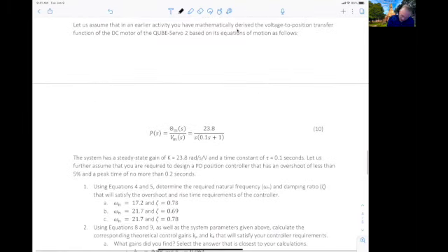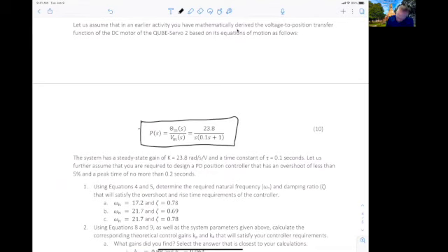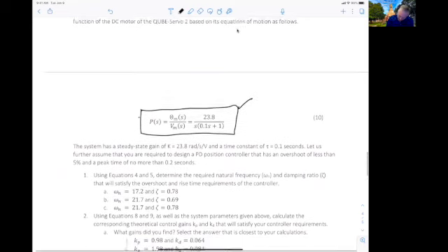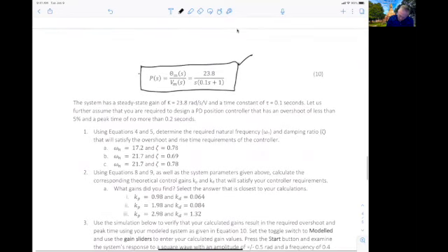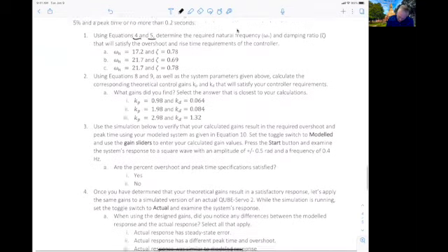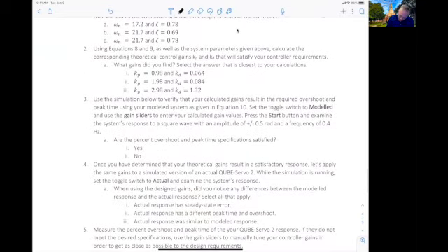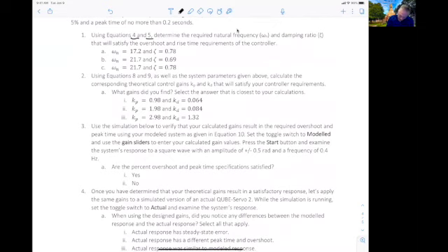Okay, so we're going to start off, and you're going to assume that this is given. We've already done labs to get you in the ballpark. Maybe your answers turned out differently, but let's go with this as the model. From there, the lab is just working through and figuring out how the equations work. And so from equations 4 and 5, you'll choose the omega n and zeta parameters. And once you have those, they give you the right time response. You plug into the next formulas and you get the Kp and Kd gain constants.